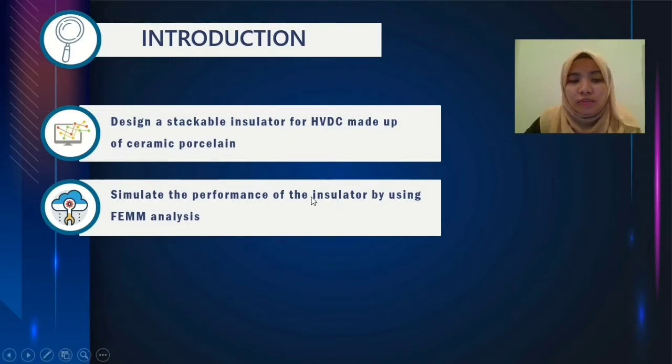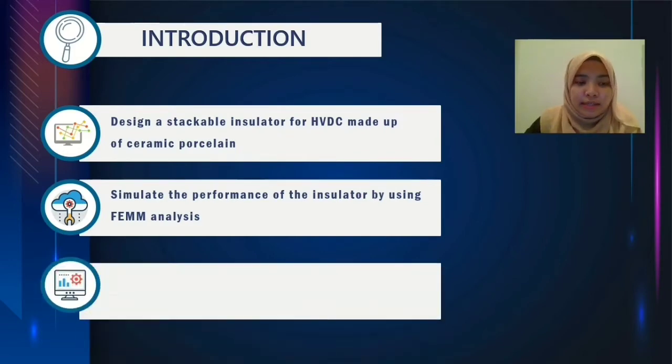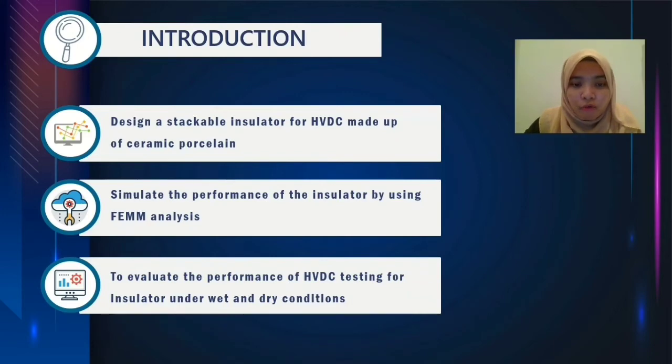Next, the simulation of the performance of the insulator by using the FEMM analysis. We simulate the performance of the insulator by using FEMM analysis, and we got the graph for the voltage distribution and also the electrical field strength. Next, we evaluate the performance of the HVDC testing for insulator under wet and dry condition.